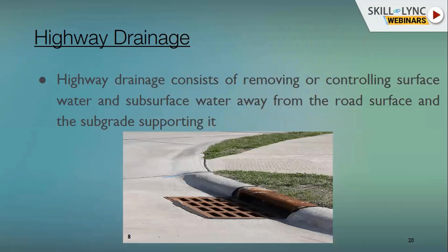One is giving a cross slope along the section of the road, so that we can drain off the water and collect it in the drains at the edge of the carriageway. Or you can give a cross drain along the section of the roads, depending upon the scenario of the roads. If it is in different sections, we can give that as well.